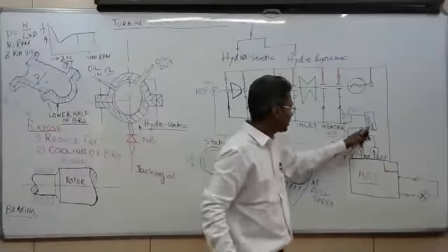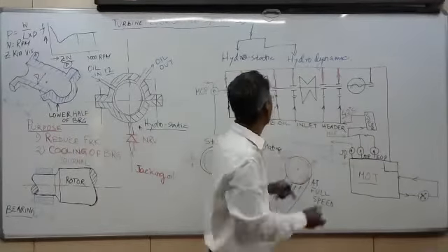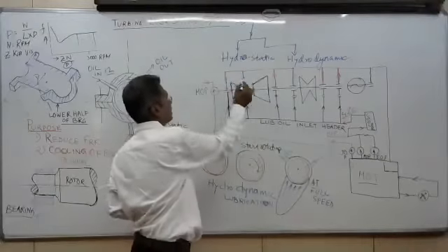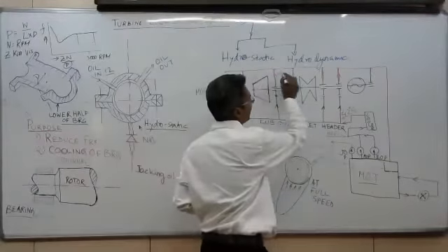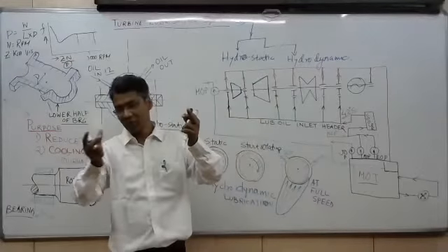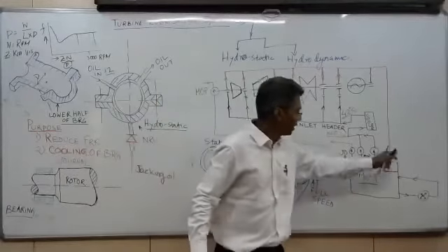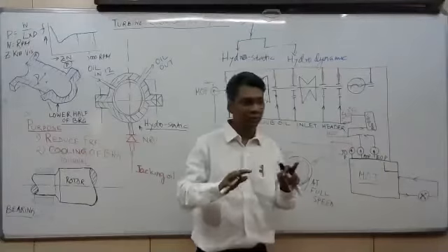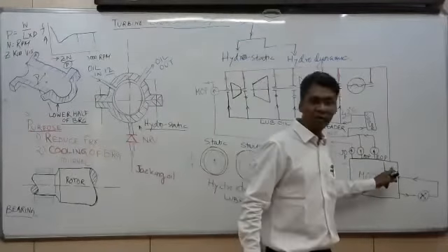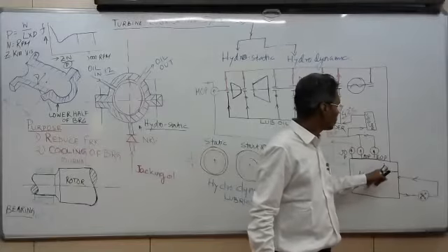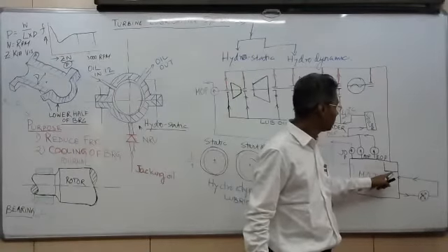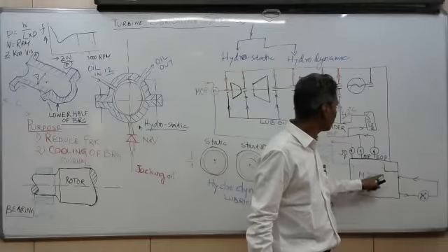At 40 degrees centigrade we are providing oil at the inlet. These are the oil drains. The drain out is connected like this to the header, and the header is designed in such a way that oil flows by gravity to the tank. The tank is placed below the turbine floor, so oil flows by gravity to the corner of this chamber and goes to the main chamber.